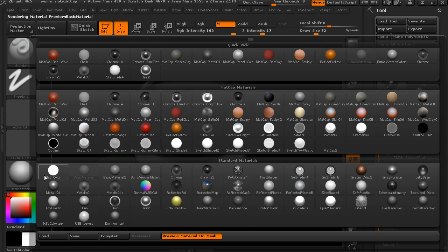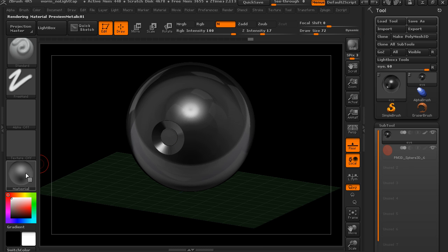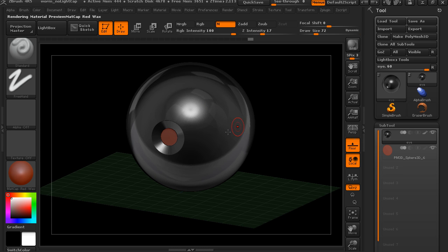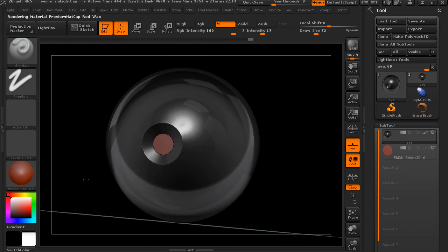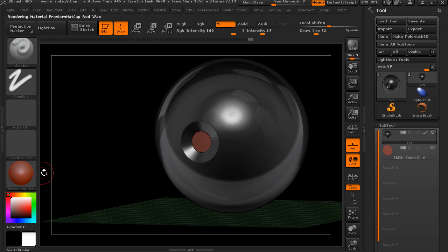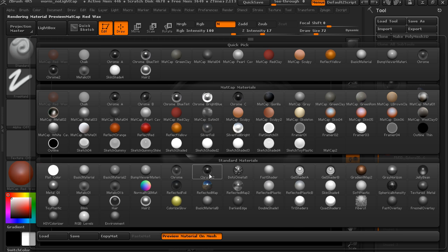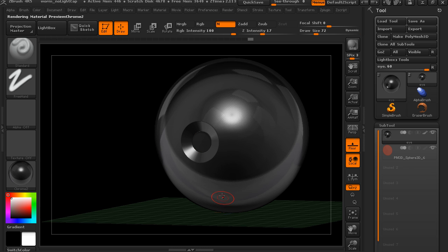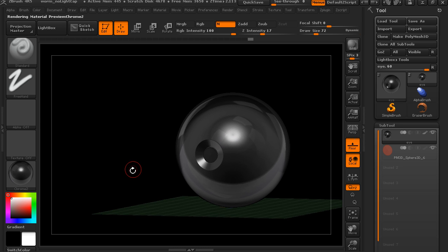So we no longer get the flexibility of jumping around to different materials, because we've now assigned a particular material. The material is looked up in this particular material slot. So if you start to make custom materials, be aware that you want them to be in the same slot so that they can keep their assignments to whatever you've assigned them to.